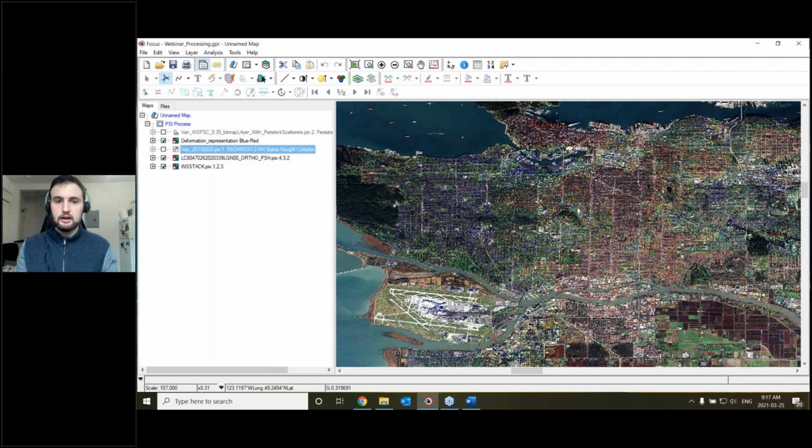What we're seeing right now is blue regions are representative of more subsidence, while the redder regions are areas of more uplift. And there, of course, are other colors for stability. Each point has a variety of measurements built into it over the time period, so we can actually analyze it and visualize temporally how the points or the area is changing.